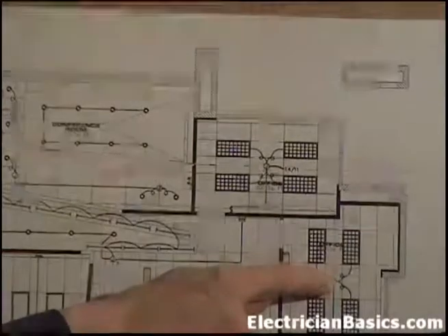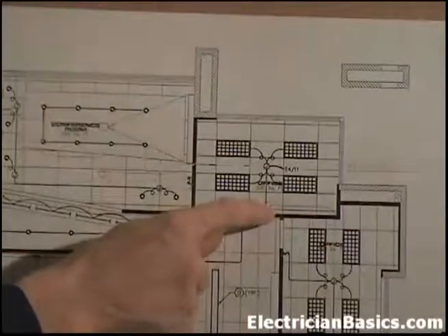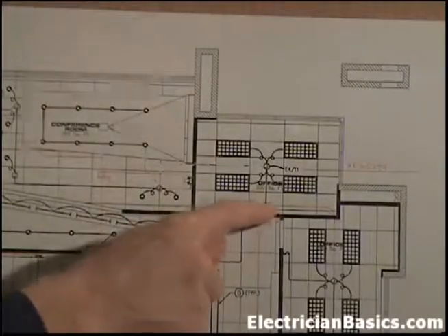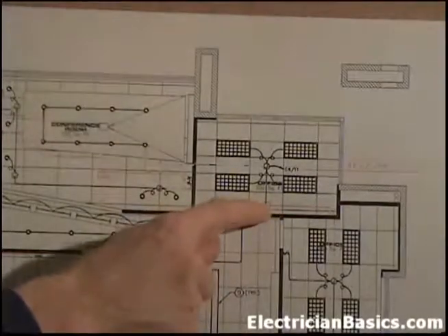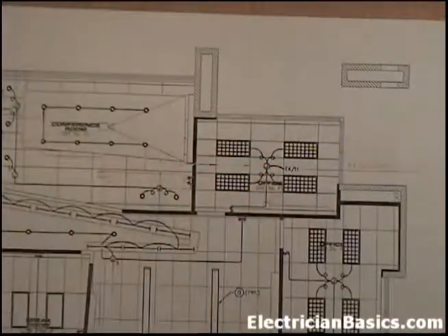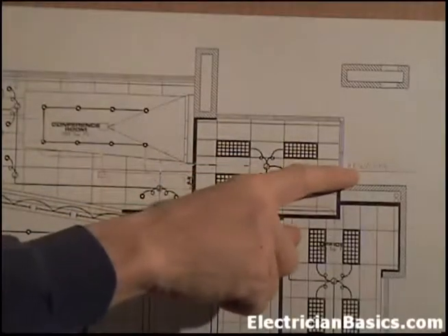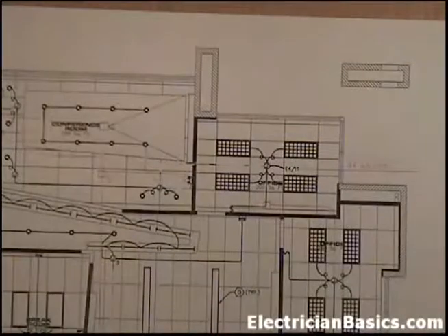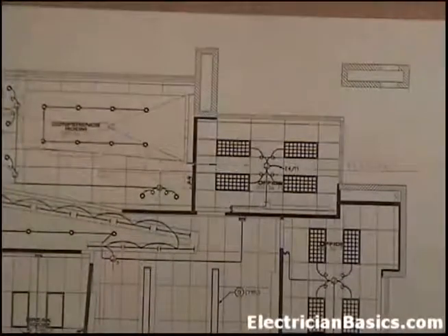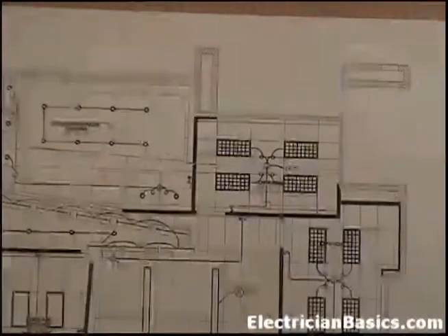So we'll just extend this pipe, redline it up to here, put it in the junction box, and then we'll hit this switch with it and come out through here up to these lights, and we'll run our circuit 11 in that same box. And I put a note here out to the side, home run with circuit 9. So you can look for that. Okay, we're going to go down and look at what we did at circuit 9 to that home run as well.